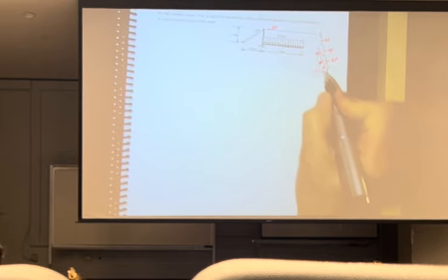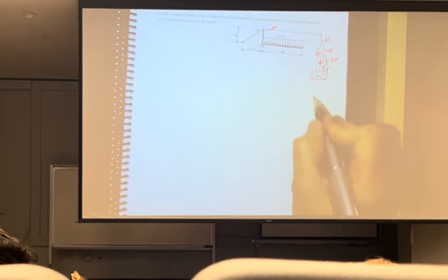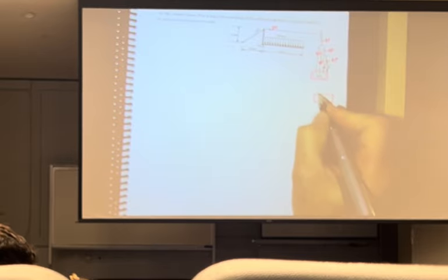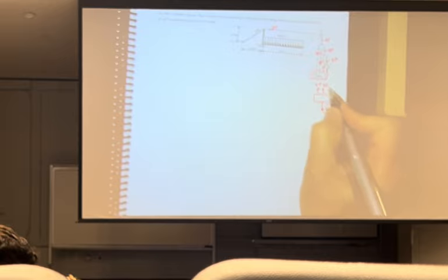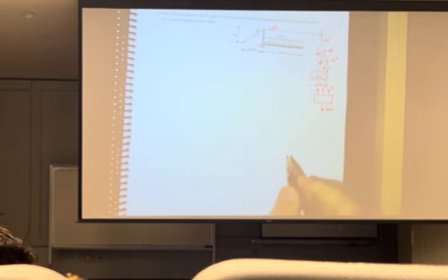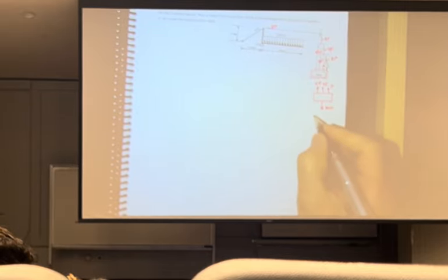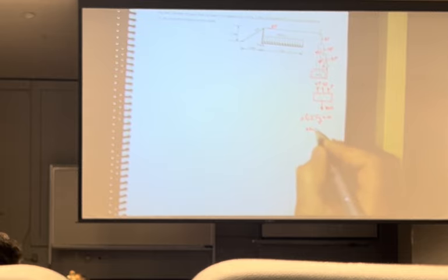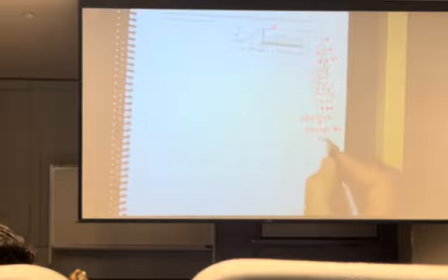Now if I isolate this right here, I'm going to have a free body diagram that says 800 down, upwards 4P, upwards 2P, upwards P. That is sum of forces in the Y equals 0, positive up. 4P plus 2P plus P basically must equal 800, or P is equal to 114.28.